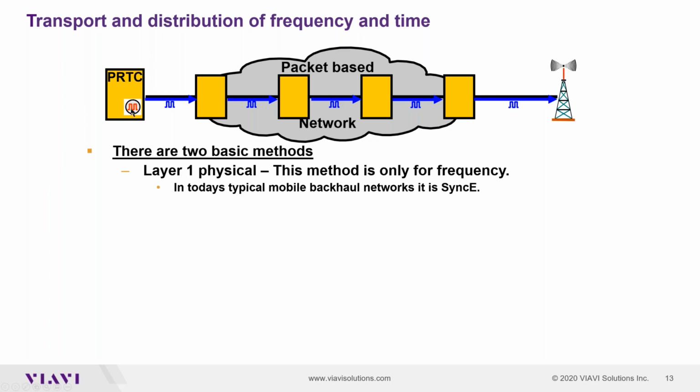Here we have our reference oscillator, our reference frequency, our reference clock, and we have maybe a 10 gig Ethernet interface, and this 10 gig Ethernet has a TX clock here. The port here will take this receive clock and recover it, and will internally take this clock to tune its internal oscillator, and use this oscillator to generate on the other side the TX clock for its 10 gig signal, or for its 100 gig signal, doesn't matter.